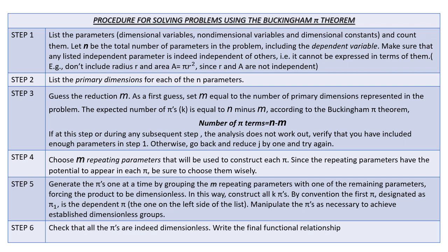Once we identify the total number of terms, the next step is to write the dimensions for each and every term. That is very important. When you write the dimensions, you should cross check twice whether they are right or wrong. Even if you make a slight mistake, though you know the concept, the whole problem would be wrong from the beginning. Once you identify the total number of variables, you write the dimensions for all the variables.